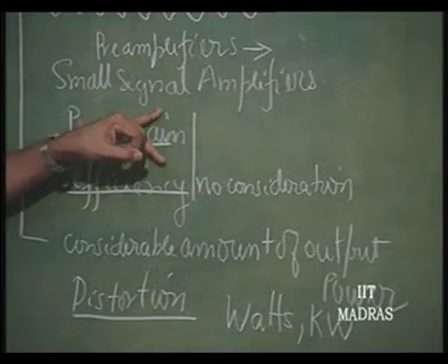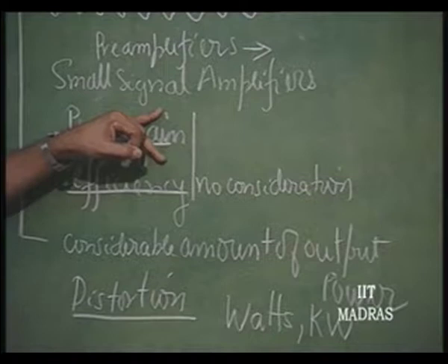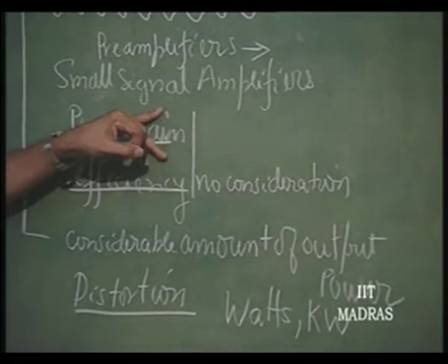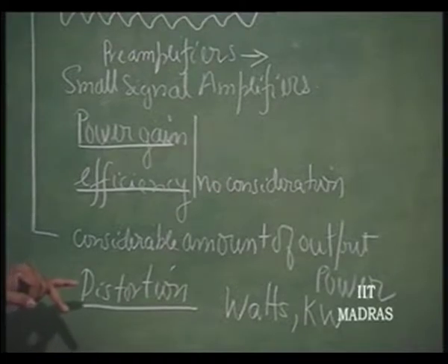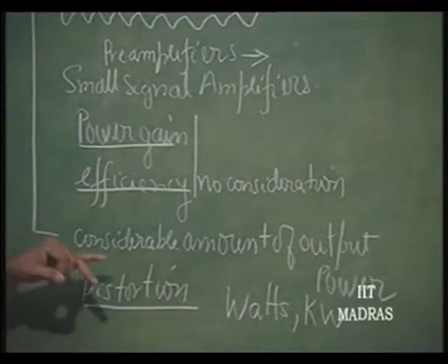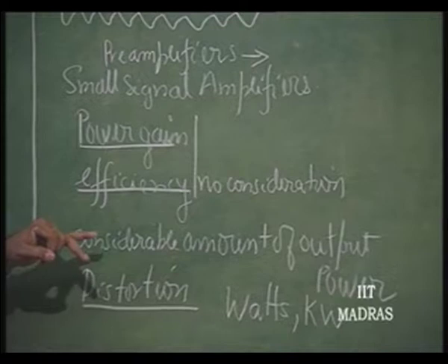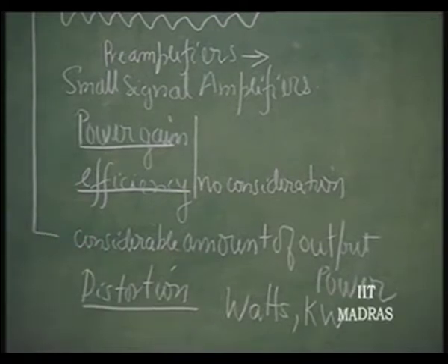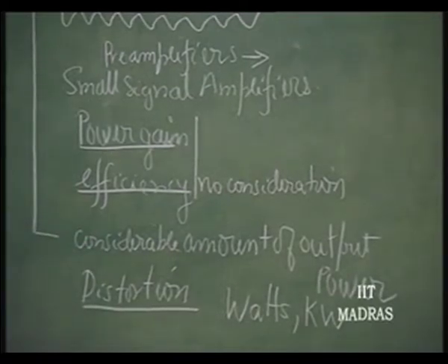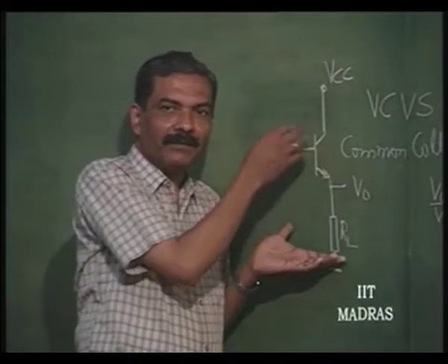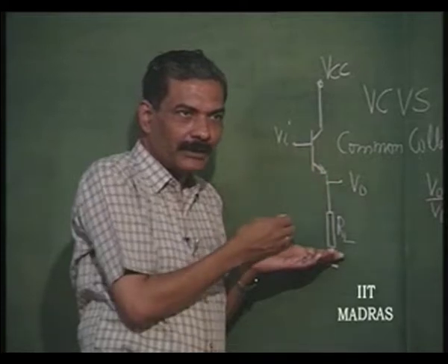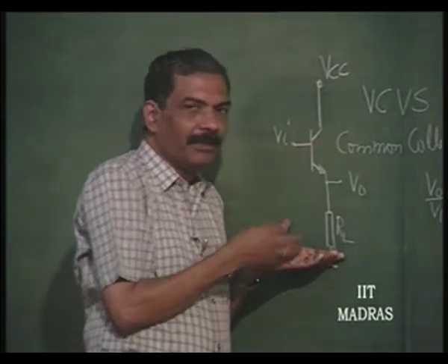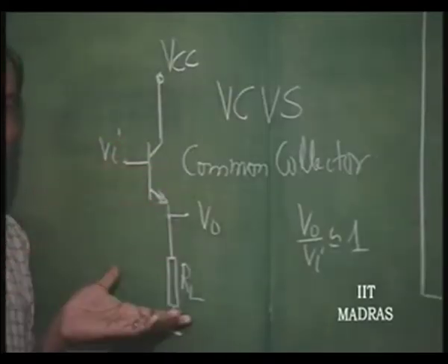It is not, because the signal is varying considerably, and therefore, in power amplifier analysis it is futile to discuss distortion without considering the nonlinear aspects of the device. So, the nonlinear aspect of the device comes into picture. If it is a feedback structure, the nonlinearity is automatically reduced.